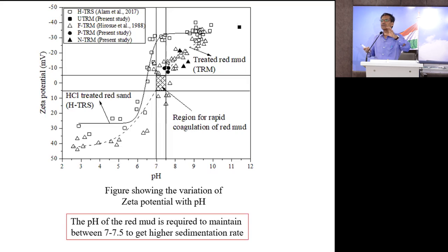Even I visited some. There is a similarity between BP tailings and red mud. BP tailings also have very high pH. Those who are from the steel industry can tell, it is also more than 11.5. And both look exactly similar. BP tailing is beneficiation plant tailing in steel industries. It also looks exactly red, like bauxite residue or red mud. The pH is also similar, 11.5, 12 and so on. It does not settle immediately, and another problem you will see is that it does not consolidate quickly.